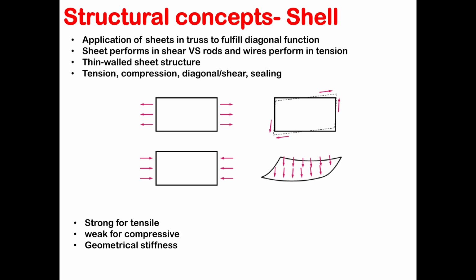But you have to keep in mind that to fully exploit the benefits of a sheet material, it may be necessary to reinforce the sheet with other elements. Without any additional reinforcement, the sheet material can easily carry tensile load, as mentioned, up to its ultimate strength, but it cannot carry significant compressive loads.